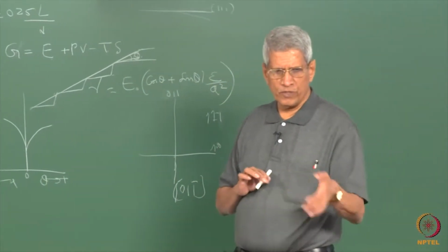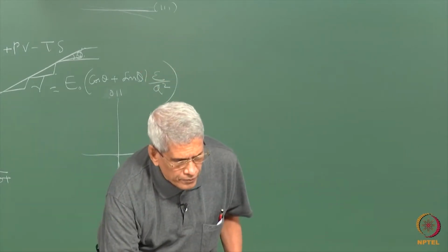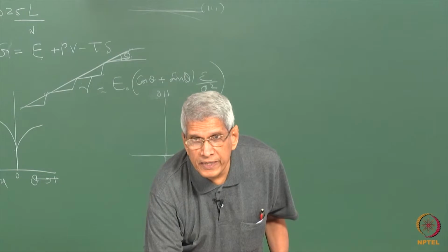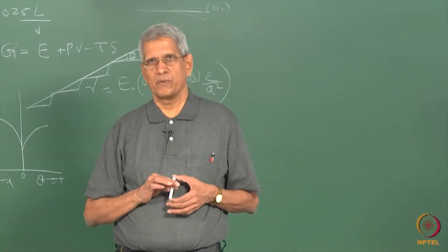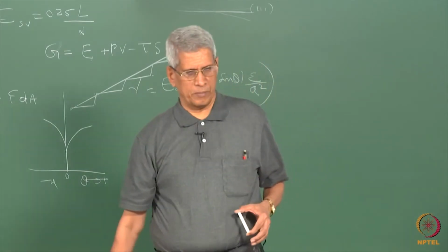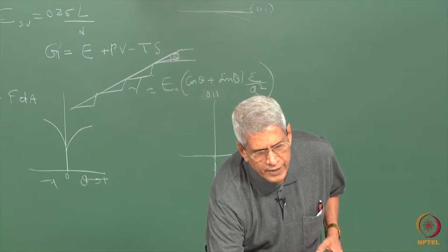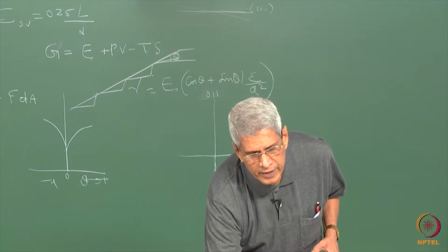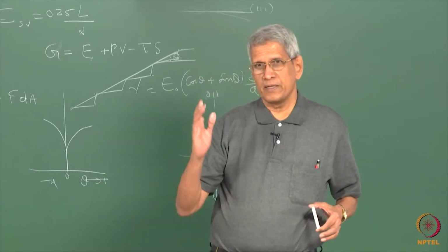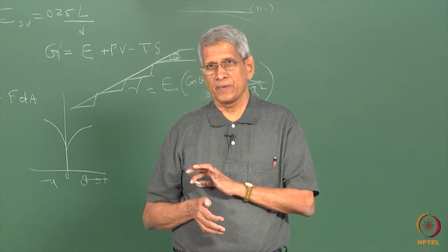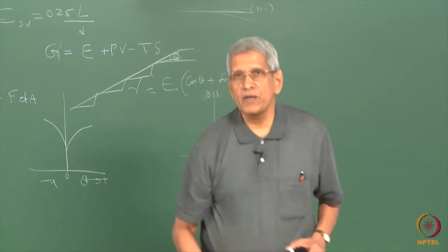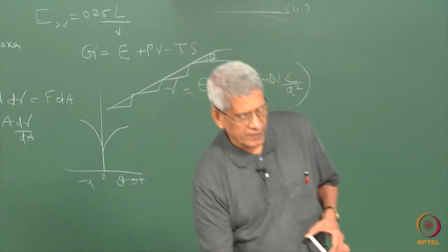This we can do using what is called a Wulff plane. If I draw a vector from here to this surface, and draw a plane normal to this vector, that is one surface which the material can have, correct? That represents the surface, and this point represents the energy corresponding to it, because the coordinates here are crystallographic directions which are chosen. Any plane normal to this vector will give that plane. So if we draw a plane perpendicular to this vector, that will represent the 110 plane. That is essentially what is being shown.